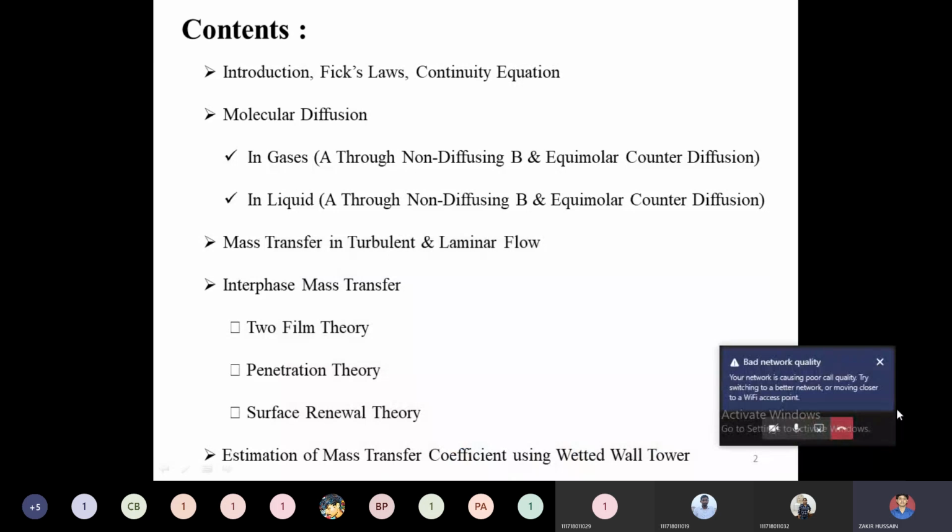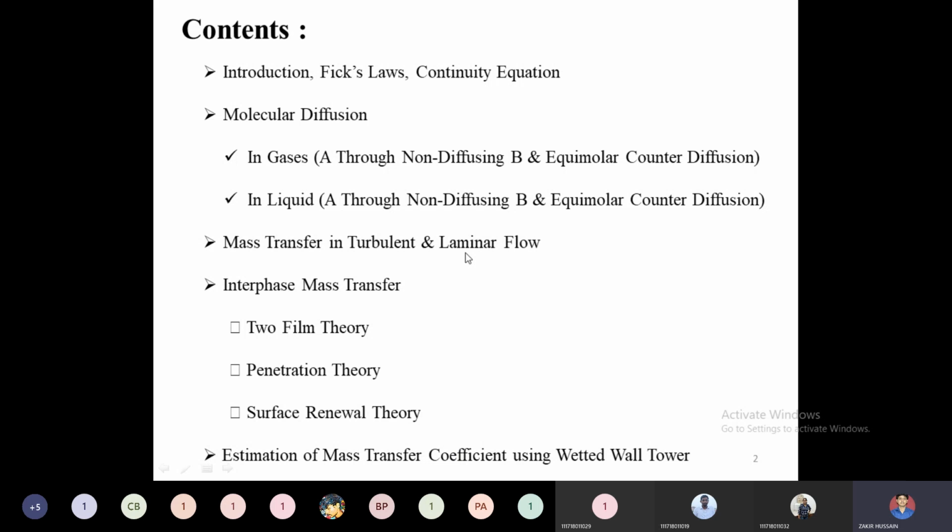Usually every mass transfer operation will have more than one phase. So for more than one phase, it is very convenient to evaluate the mass transfer coefficients. It will give the diffusion rates and everything. So mass transfer coefficients are the usual criteria applied to determine the mass transfer in laminar flow and turbulent flow, where there is a convection of mass, similar to heat transfer, where for conduction we use Fourier's law of heat transfer, and where there is convection, we use Newton's law of cooling.